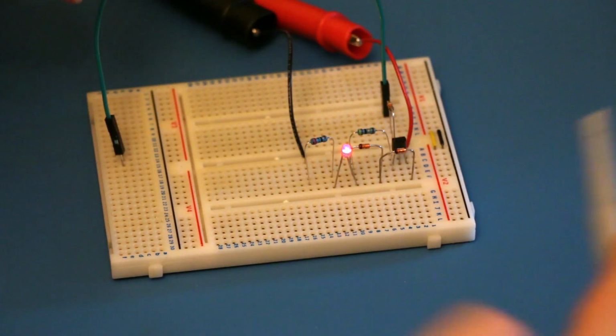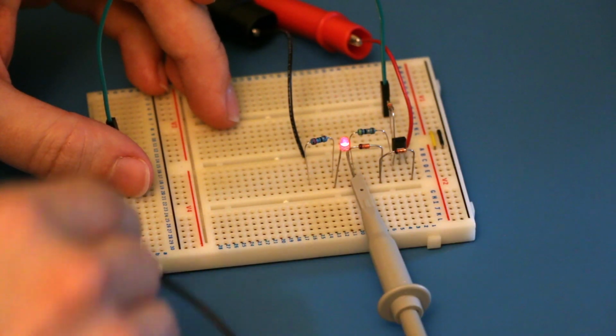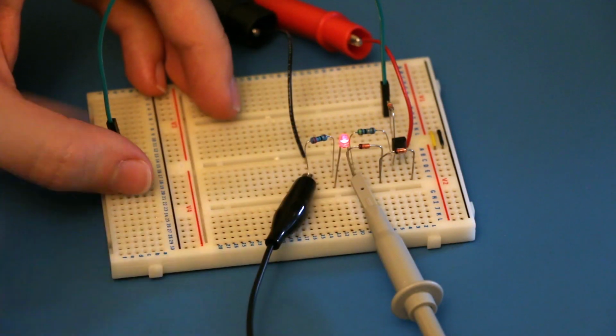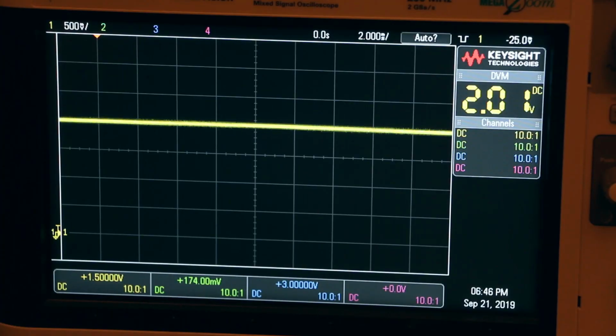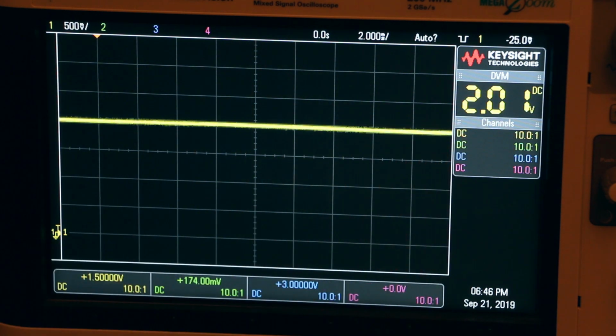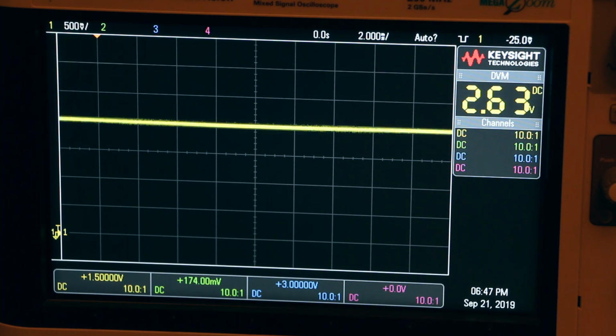Now, to check the voltages and things, we can hook that up to the scope. So I'm just going to take the LED's positive and the 0 volt rail, and that should see the same voltage that our LED chain will get. That green wire is currently floating, and as you can see, the LED chain would currently be supplied by 2 volts. If I bring that floating wire now to ground, there's a step up to approximately 3 volts, which should give us the ability to communicate with the LED chain, no problem.